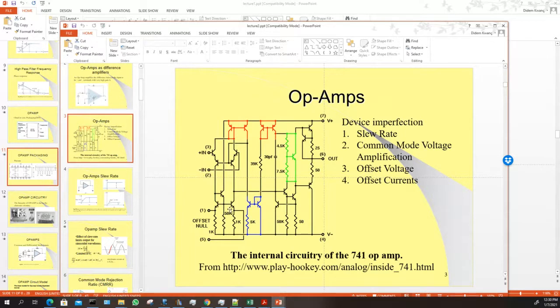In your electronics classes, initially, you'll learn how to analyze one transistor circuit. And then you'll talk about 2 of these connected together, like an input current mirror, for instance. Each of these bits of the circuit has a different role. The role of this part is to make sure that you have a very high input impedance, so it won't draw any current in here. And then you also have this matching between the 2 to get rid of any biasing current. And then this upper part is to protect the voltage that you're applying from the power. And then this part does the actual amplification. So each of these stages has a different role in your design.